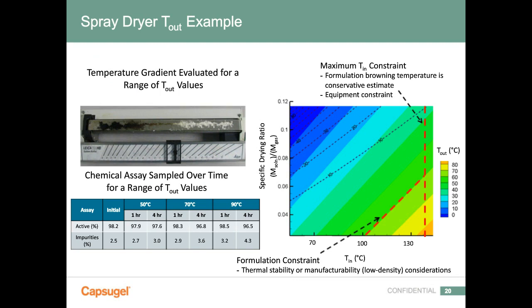Now, this is actually the critical parameter when understanding spray drying and formulation components that are added in. So the inlet, as we just talked about, can set up the actual thermal profile, and then also in combination with how insulated the dry chamber is, those inputs now give you the output of the outlet temperature.